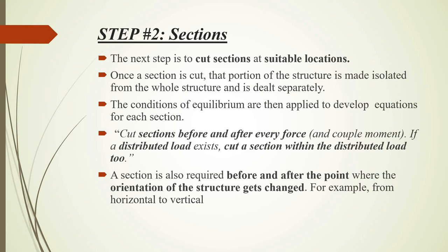A section is also required before and after the point where the orientation of the structure gets changed. So if you have a frame with multiple orientations, you are going to cut a section when the orientation changes, for example, from horizontal to vertical or the other way around.